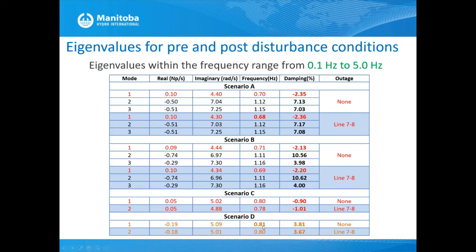So the frequency of interest, where we want the power system stabilizer to provide leading phase, is about 0.7 to 0.8 hertz. But that will impact all the modes in that frequency range. So that's why we also plot other modes in the frequency range.